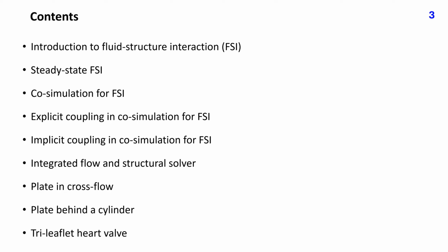Flowcharts of three solution approaches are described. Finally, simulation of fluid structure interaction is demonstrated on three examples: flow around a rectangular plate in crossflow, flow around a splitter plate behind a circular cylinder which can rotate, and flow in a tri-leaflet prosthetic heart valve.